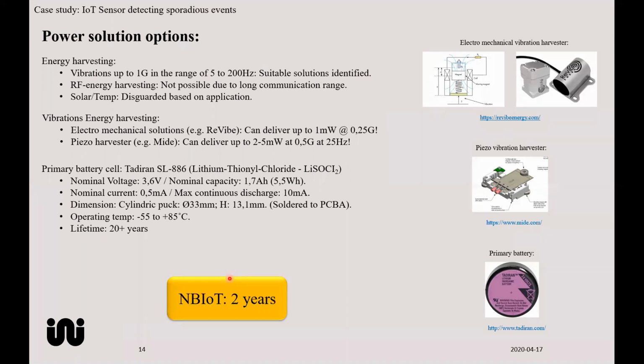But the very low power consumption of BLE long range actually, on pure mathematics, would work for 174 years. Of course, this is not true because the battery leakage is the limitation itself. But it shows that we have a huge margin between the capacity of the battery and the energy consumed by the application. So we concluded that we should be able to use the lithium thionyl chloride battery for this application.